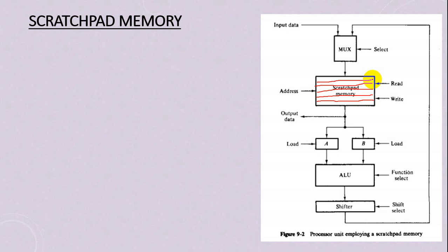So what do we see over here? Simplicity. Low cost, because we don't need to connect separate registers separately with the buses. So in SCRATCHPAD memory, we use a single piece of memory, and each cell of the memory is treated as a register.